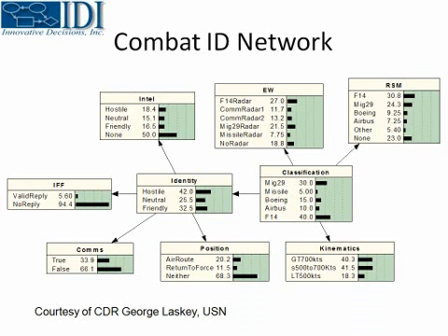Electronic warfare. So if that aircraft has its radar on and it's transmitting, you can look at the pulse width, the pulse repetition rate, the frequency, etc., to identify what kind of radar it is. And then the final one is called RSM. RSM is basically a Doppler phenomenon, where when you send your radar pulse out and it hits the moving parts of the engine of the other aircraft, there's going to be a Doppler shift.